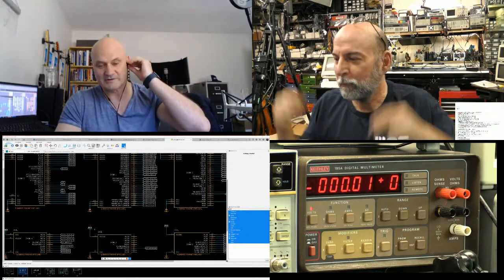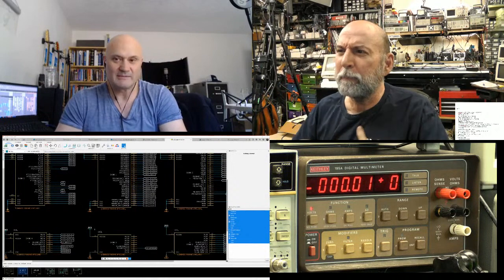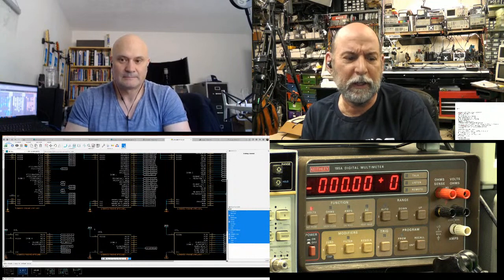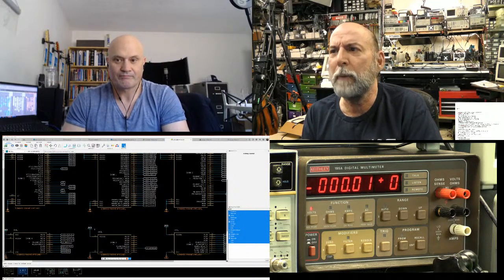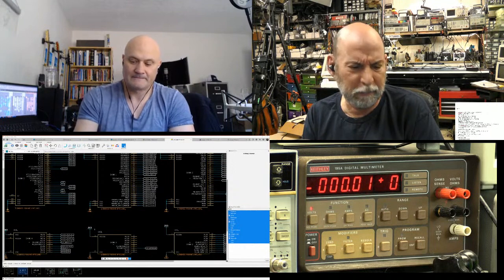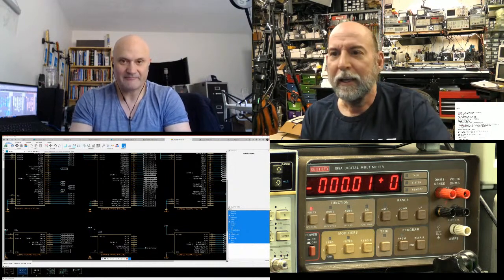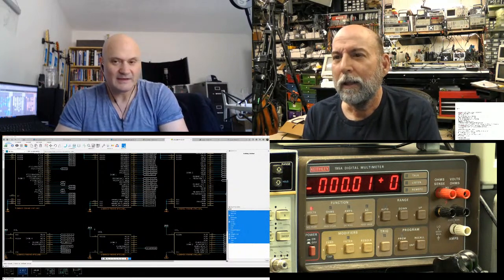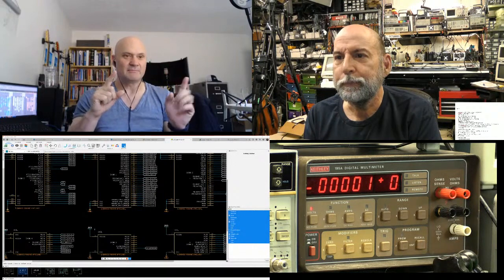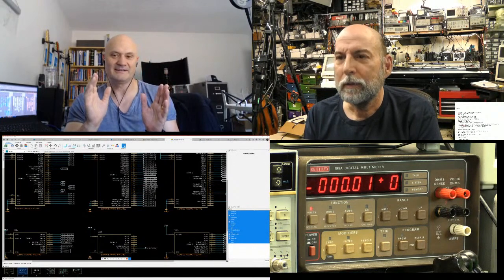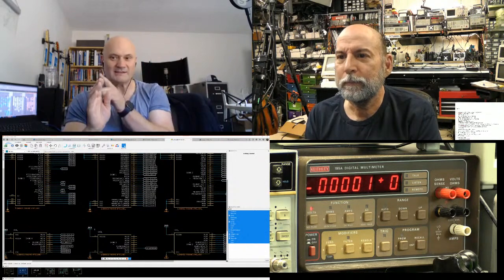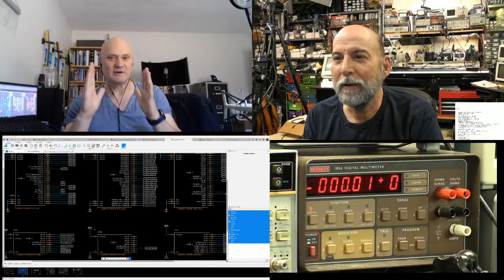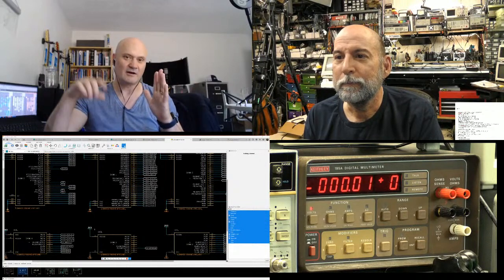I remember doing pitch shifting using the old bucket brigades. They were the CCD bucket. That's a real old way of doing it. And they were just noisier. Yeah, because what you do is you record a wavelet and then you play it back at twice the speed to get an octave higher. Right. But you have to play it back twice because you now have to invert it on the way down. Yeah. But by playing it back twice, there are no even start and stop points on an actual waveform.